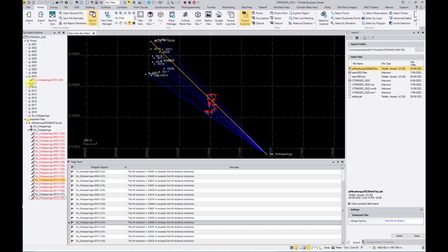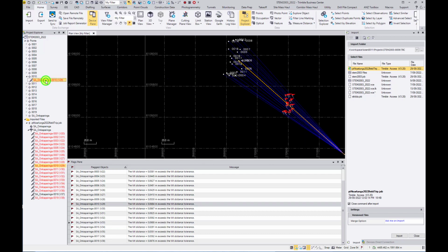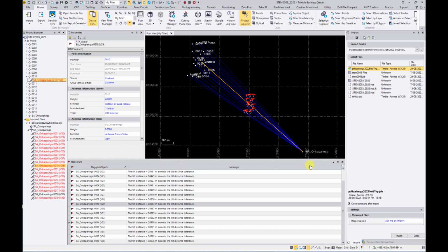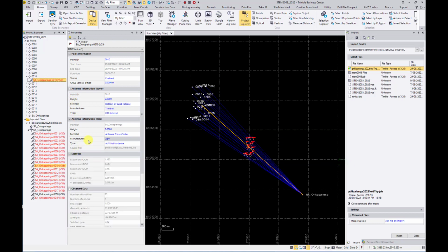On top of that, we then need to add the anticipated error. So if I come down here, I can see that my horizontal precision was 1.1 centimetres. Add that to the 9.8 and all of a sudden we now have nearly 11 centimetre error.